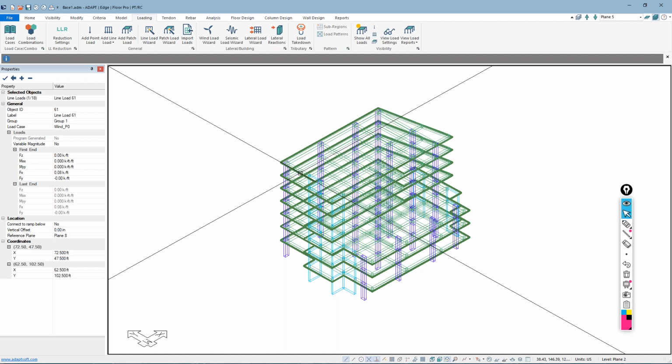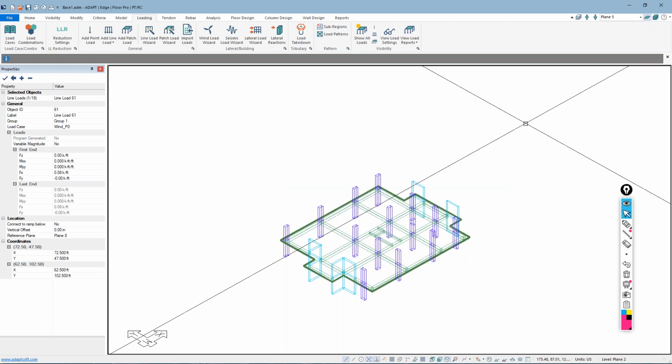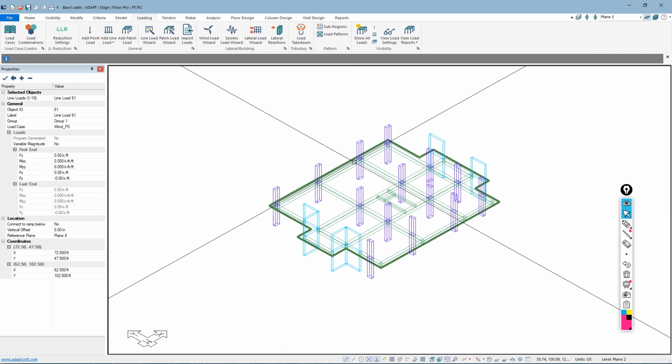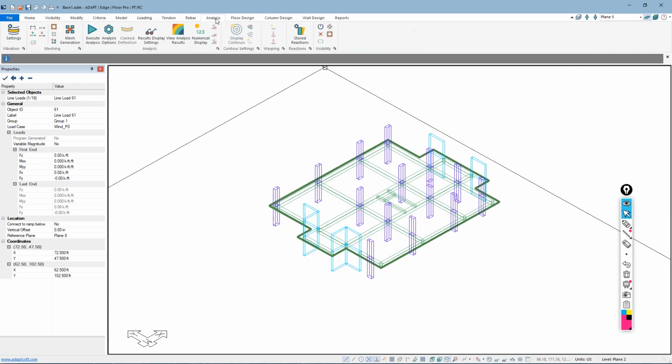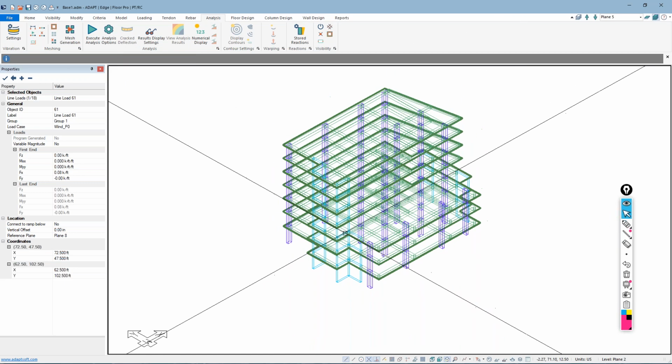That's primarily due to just the historical nature of this program, which really, when it was first released many years ago, this was just a single level program, and we had a way to calculate the cracked deflection for just a single level slab. That still applies, but this crack deflection option does not apply to just general global analysis in the structure. So we're left with using these usage cases.